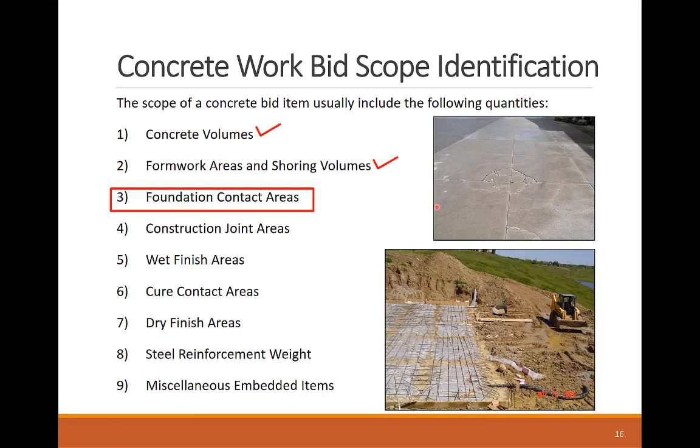Although it's not part of the concrete structure, the soil under the foundation needs to be fine graded and compacted to provide a clean surface for the concrete, rebar, and formwork crews. The civil contractor who excavated the soil is typically required to finish the soil to the required foundation elevation with a rough tolerance that's not sufficient to create quality bottom surface of the foundation.